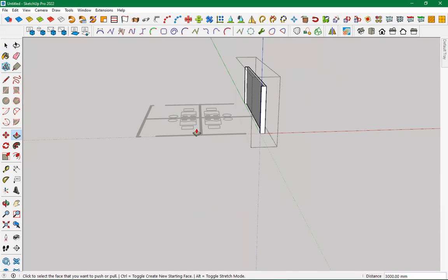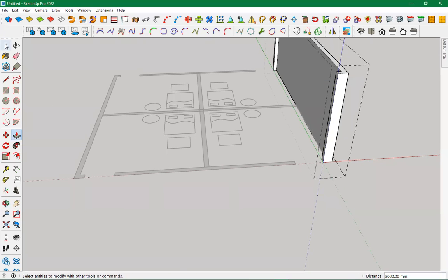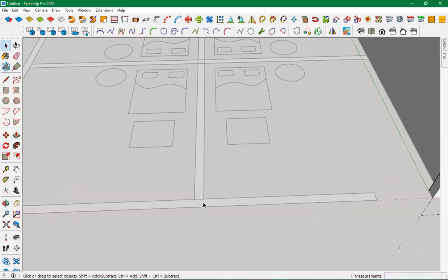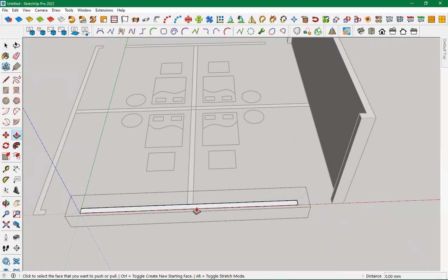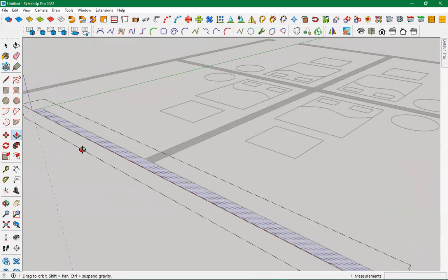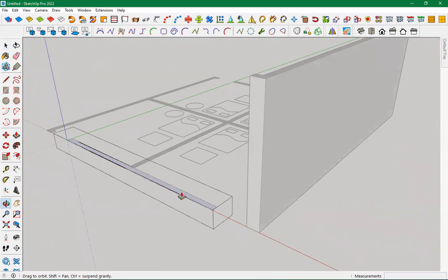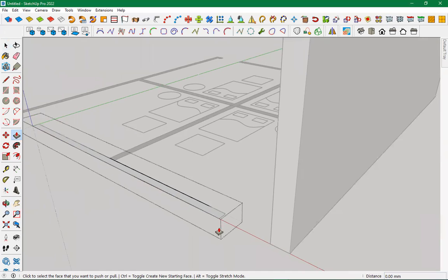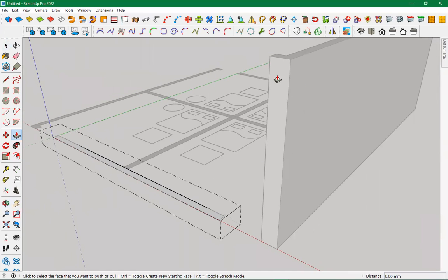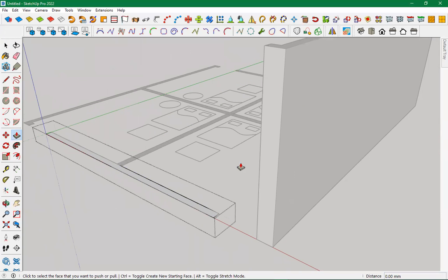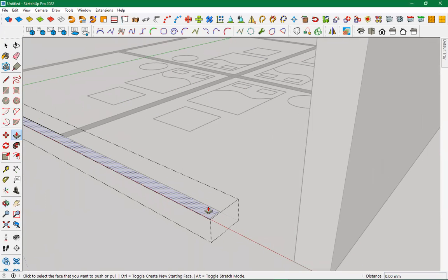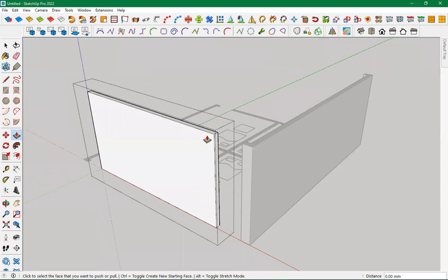So I'm doing this. First of all, pick tool again, select another wall. Now, instead of me to click and type 3000, I'm just going to double click. And once I double click, it will be extruded to the previous height. Yes, it will take the previous height once I double click on it. So SketchUp remembers your previous actions. So if I just double click here, like so, see, it's equal to this height.